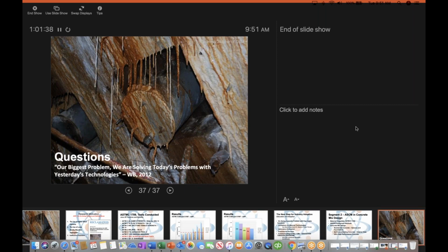At certain dosages of silica fume, above 7.5%, you start seeing not a toughened hydrated cement matrix, but a more brittle one, more prone to catastrophic and brittle failure. With the Juno XP, we see the opposite. We might not see that instantaneous pozzolanic reaction, but that mineral component I spoke about earlier is going to increase the tensile and shear capacity of the mix, in lieu of reducing the tensile and shear capacity like we see with the silica fume or microsilica.